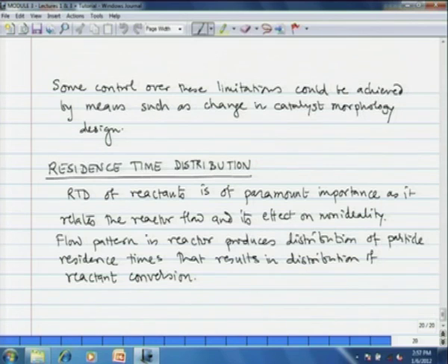It is usually performed using some tracer material, or easily detectable inert tracer material. Tracer enters the reactor system in the same manner as the reactants and uses the same flow rate and the carrier fluid. The tracer concentration at the inlet and exit of the reactor is monitored continuously, and the collected tracer response data is used to calculate the residence time distribution pattern in the reactor system.